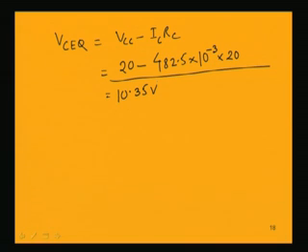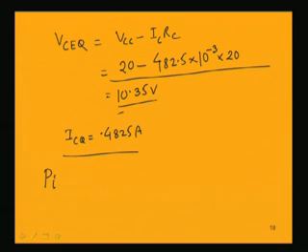So, now you see that this is a very high value of voltage and a high value of current which is flowing. The DC value of IC flowing is 0.4825 ampere. So, the DC power we know now, what will be the DC power input? Voltage into current will give you the input power. So, we can immediately find out PI DC, it is VCC IC.